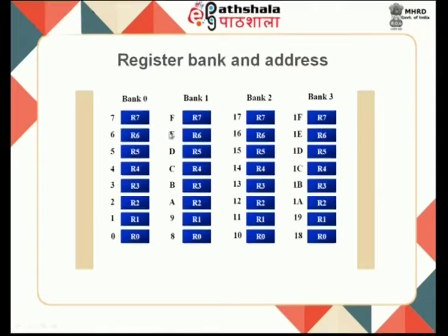So, this has been written in hexadecimal. It is given as A, B, C, D, E, F, so 14 and 15, and when it is 16 in decimal, this will be converted into 10 in hexadecimal. So, these are addresses written in hexadecimal. Bank 3 is from 18 to 1F. So, I told you 00 to 1F you should not use, it is a reserved space for your register storage.